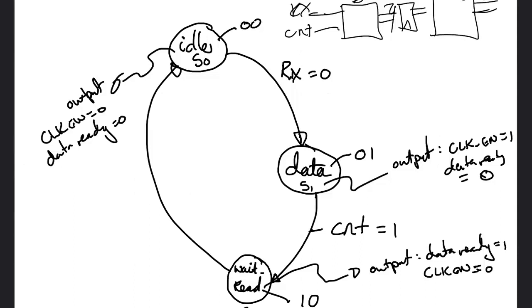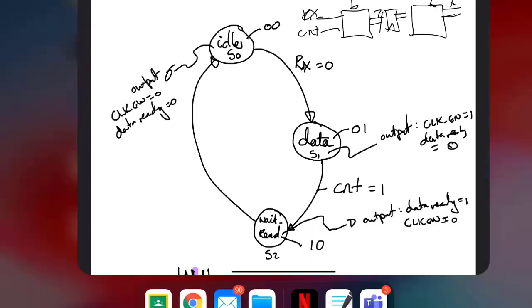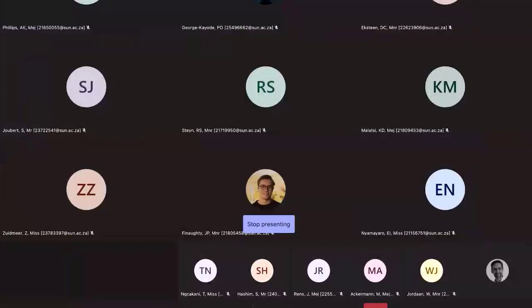And the outputs. The way that I've designed this thing to work is, again, I have a state machine, then I have a shift register that receives into the serial, into the shift register. It's driven by the clock, but then the shift enable, or the clock enable, you can decide how you design it, is also controlled by my state machine. So the one output is shifter enable, the other output is clock enable. So the clock needs to start counting as soon as you enter this state, so that you have a count max, which will obviously again be the counter output. You check with an AND gate, and then this goes high when you received all the bits and the count has been reached. And now I'm gonna shut up and have you talk.